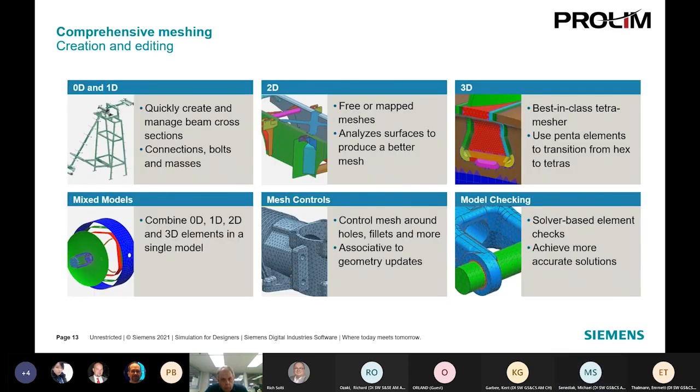Next. So just to give you a quick idea of what those different types are, the 1D mesh is something you use if you have frames, piping, tubing, that type of thing, where you really develop the 1D, which is the center line, right? Something like you would do with a sketch. You put that on and then define the type of cross section that goes on that.